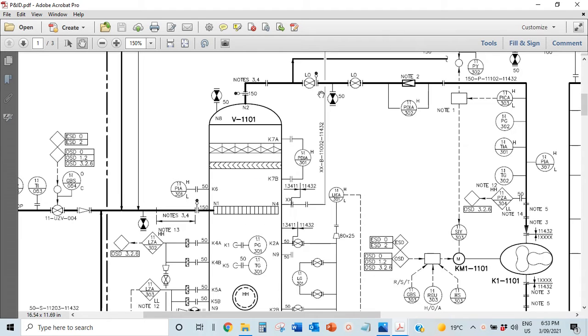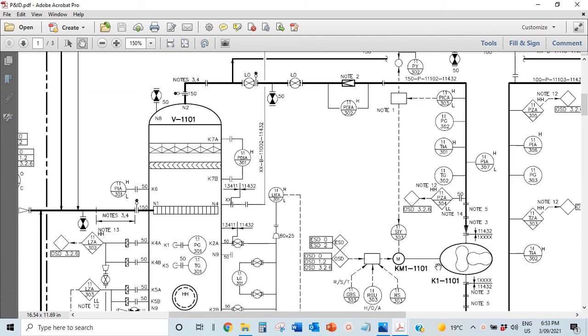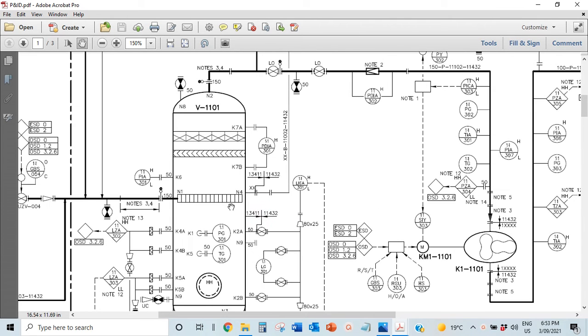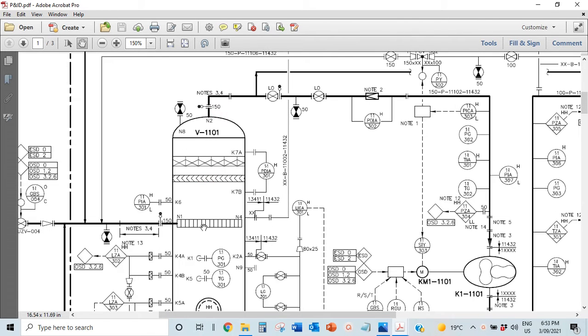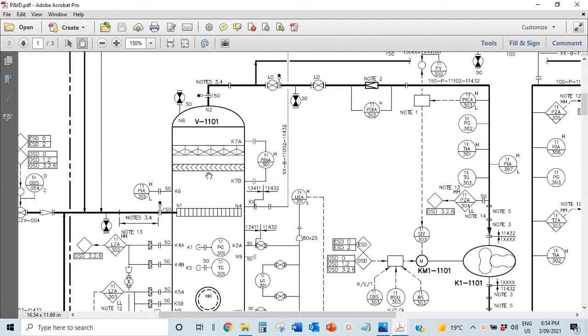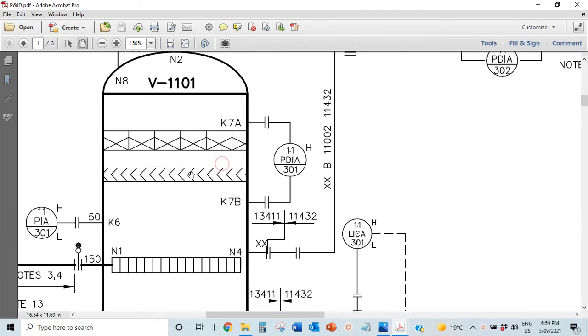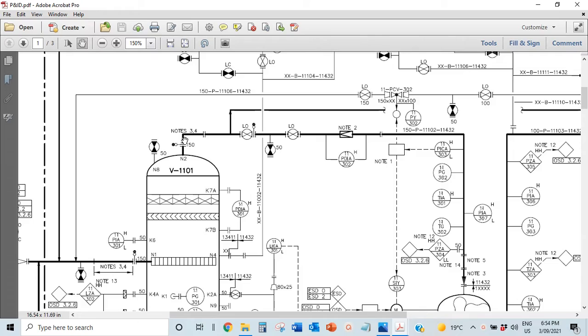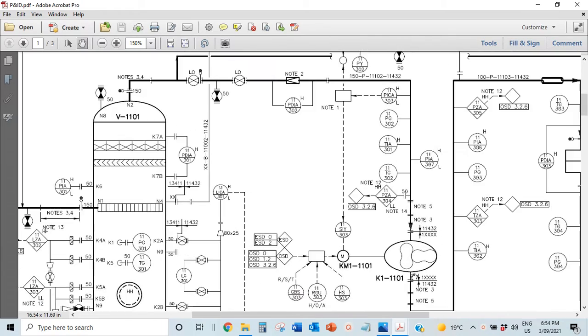The gas that goes out the top goes straight into the compressor. Remember, compressors don't like liquids. You don't want liquids in this, because it's going to damage it. It will be broken in no time if you have liquids in there. So what you want to do is trap or capture all the liquid here. These are demister pads that trap whatever liquid is entrained in the gas, and just the gas comes out here.